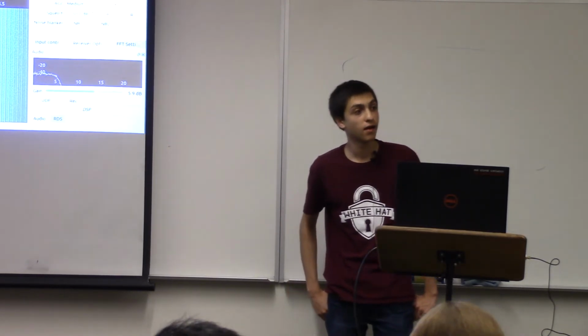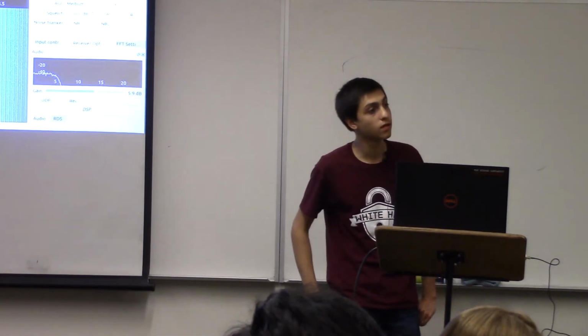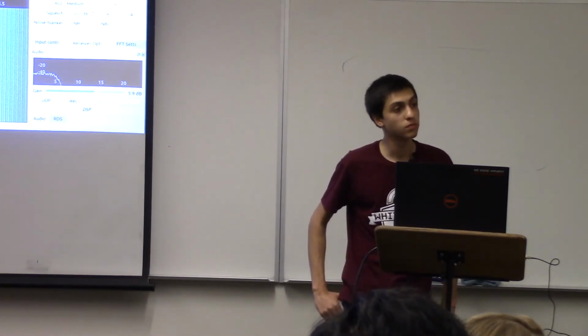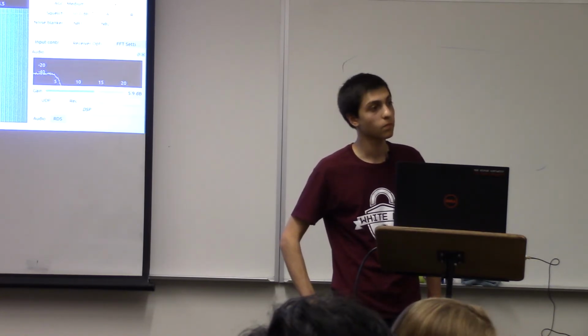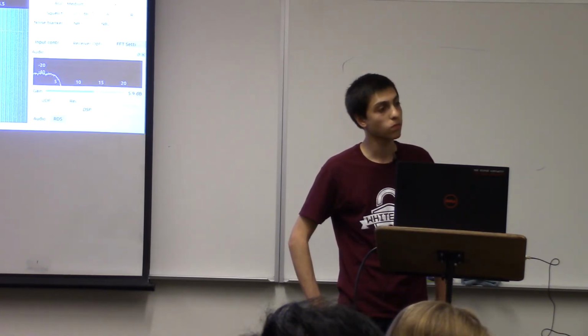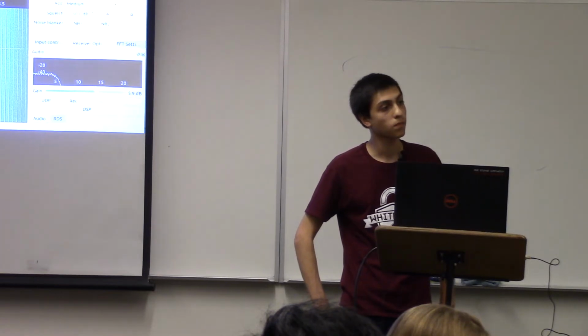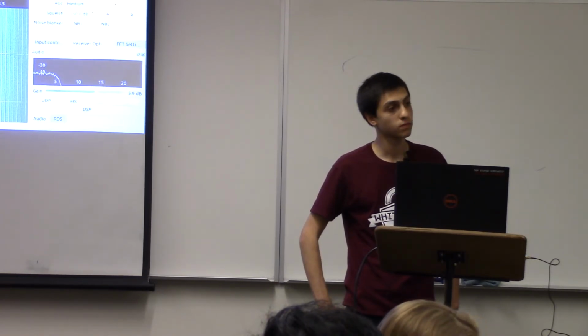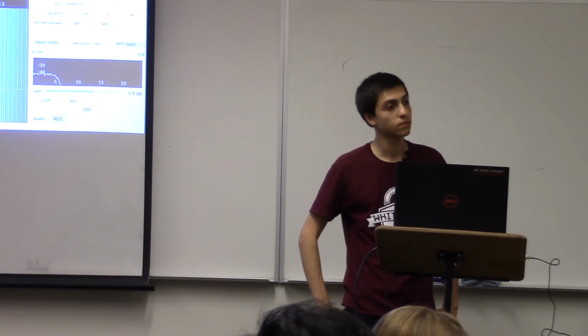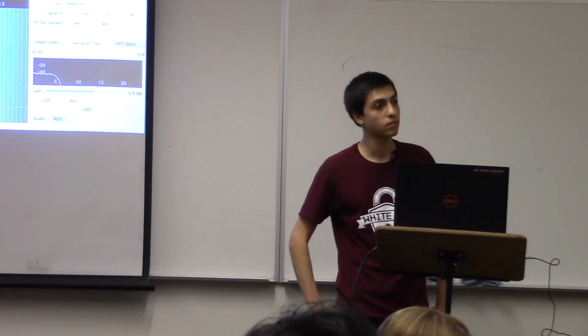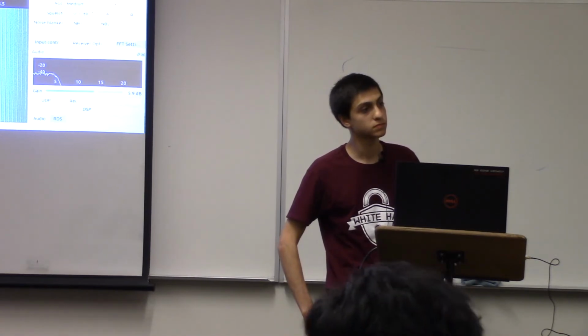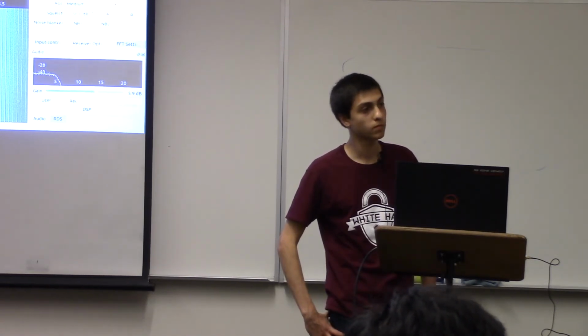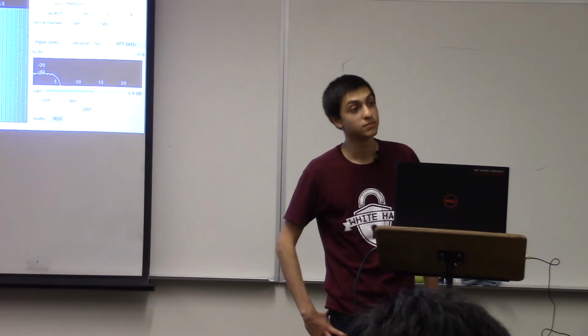And one of the previous hardware attacks you were talking about where you'd be able to skip instructions, say for the password guessing. If you had the program set up in such a way that on a correct guess, instead of continuing through the code, it would jump to some other part of code and execute the true part of the instruction, would that circumvent or prevent that type of attack?